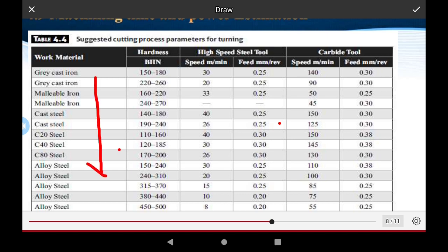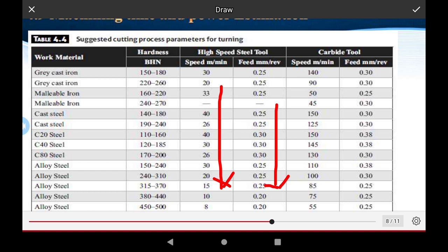This is the variation of the materials and the variation of the hardness numbers, and the feed speed of the tools, stainless steel tools used in the materials, and this is the increase of the speed depending on the operation of jobs, and feed per revolution is also required for different values, and the carbide tools also need a speed provided to the tools, in meter per minute, okay.